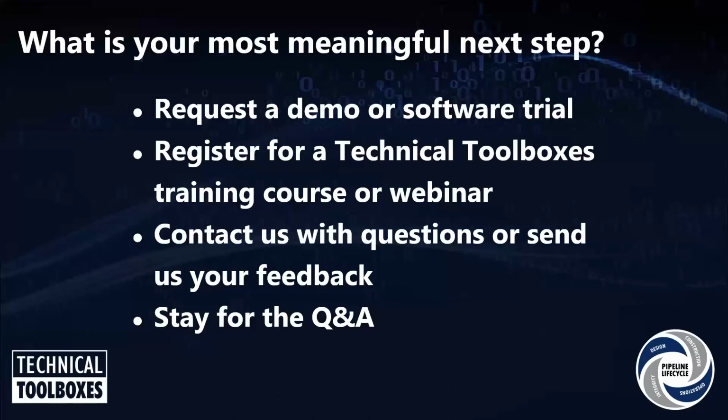That's a great question. The best way to answer that is conductive or resistive is through the earth. They're actually both through the earth, but the one you really need to be concerned about is the conductive, because it is generally where the pipe is in very close proximity to the tower line or to the ground.